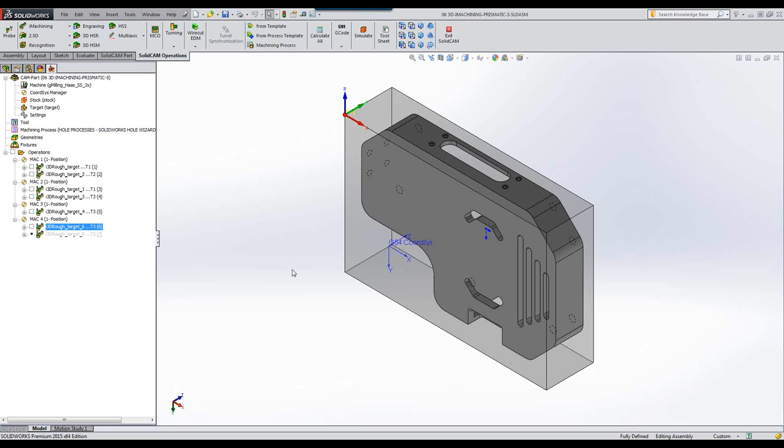Well, when you make complex parts, when you have many different pockets, many different depths, or very deep parts, as I showed you in the very beginning, it pays to use iMachining 3D because that will cut down on your programming time. In certain cases, like I showed you in the first case, it even cut down your machining time because it was able to go where the previous operation type, iMachining 2D, was not able to go, and that was checked automatically.